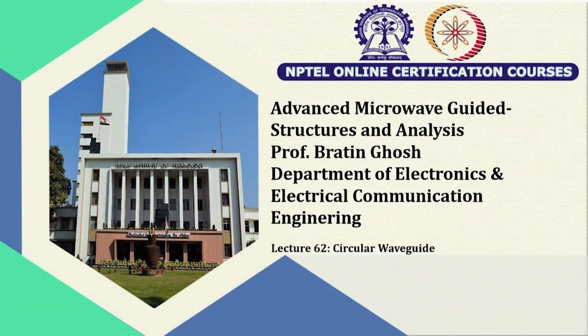Welcome to this part of the lecture on the circular waveguide. Here we are going to utilize our previous treatment of the cylindrical wave functions, particularly the TE to z and the TM to z decompositions of the solution to the cylindrical Helmholtz equation, to the treatment of the circular waveguide, and see that they yield the propagation constant of the circular waveguide in terms of the TE to z and TM to z modes.